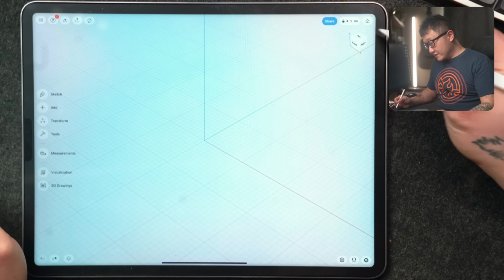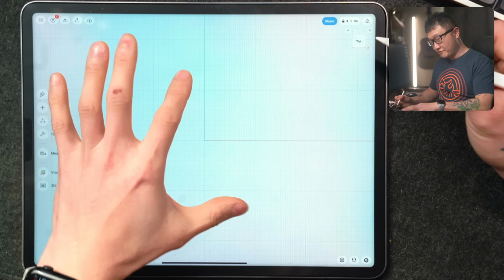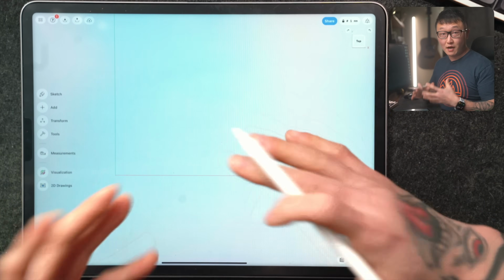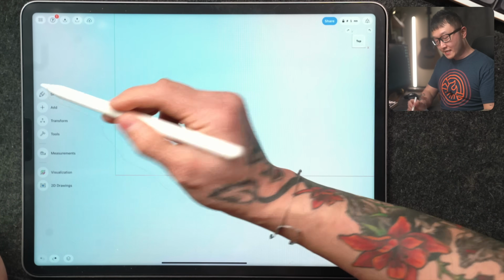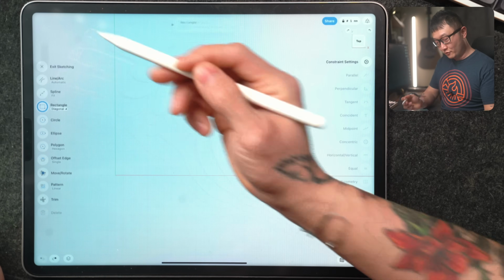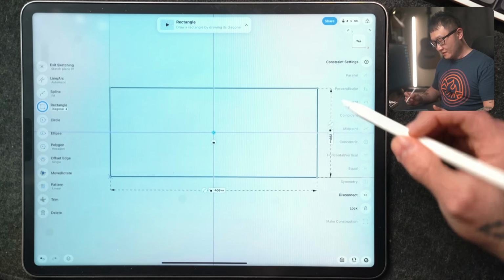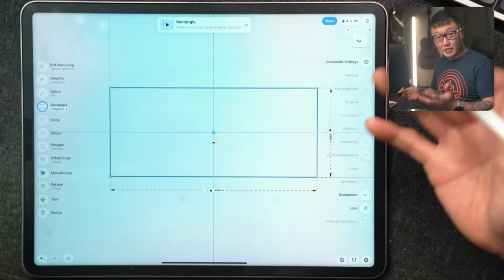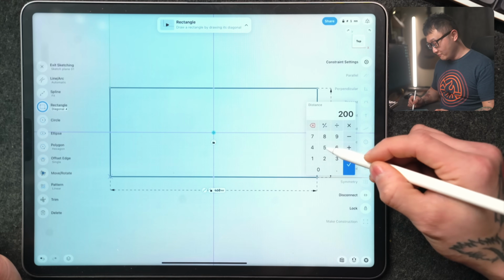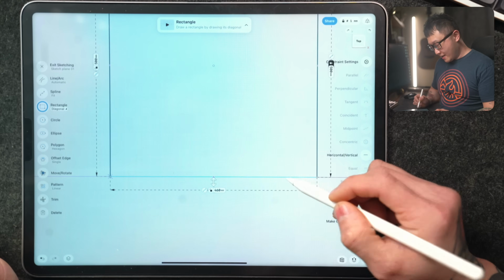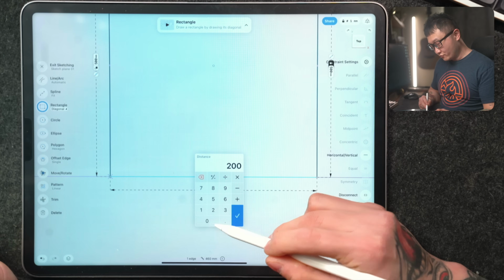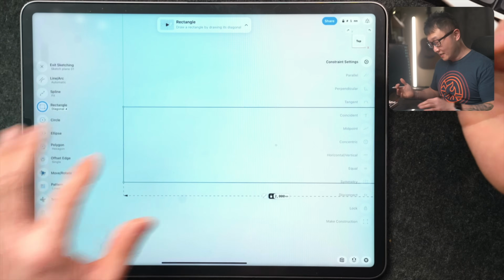So come over to the navigation cube and tap on this top face, and this will allow us to start sketching on this top plane. So come under Sketch and pick the rectangle tool, and we're going to start sketching from the origin and just drag across like that. And then we can use these text boxes to change our dimensions. So we'll change that to 500 by 2000, which is roughly about 20 inches by 79 inches.